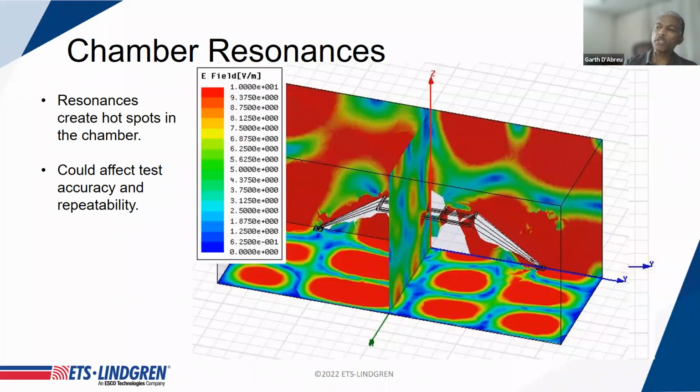And unfortunately, because it was built for higher frequency measurements, the RF absorbers did not have good absorption at the low frequencies, down in the tens and hundreds of kilohertz and a few megahertz. So what happened, as shown in this model, is that if you excite this cavity with these low frequencies, you get these resonant modes because the walls, of course, are very reflective. They're covered with absorber, but they're still very reflective because the absorption is very low from that material. So you get these resonant modes that create these hotspots within the cavity.